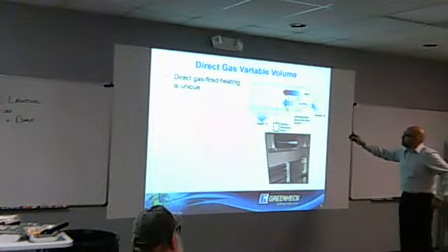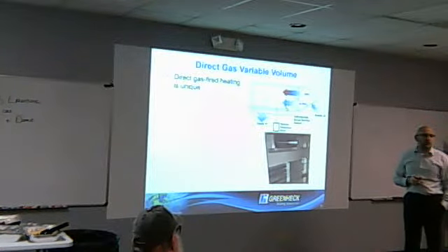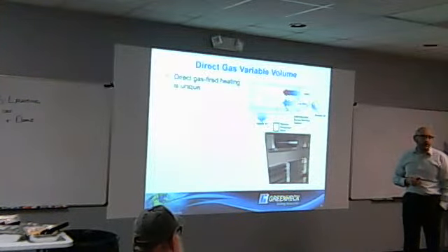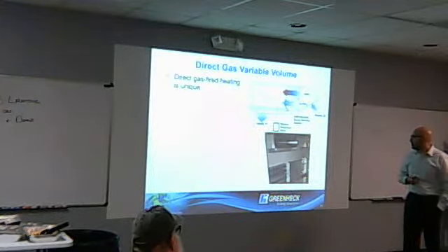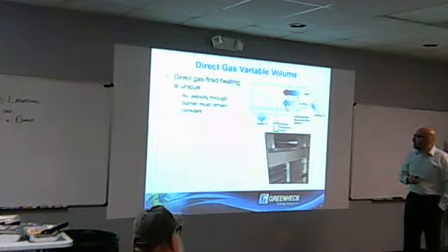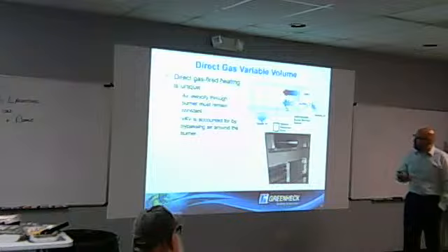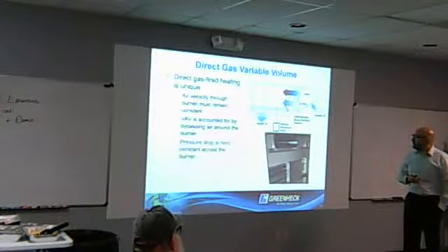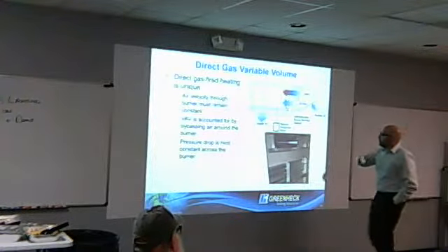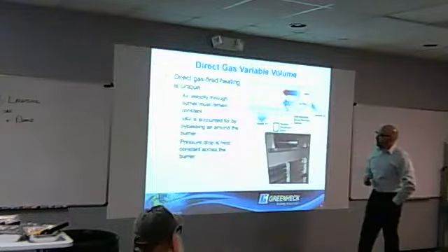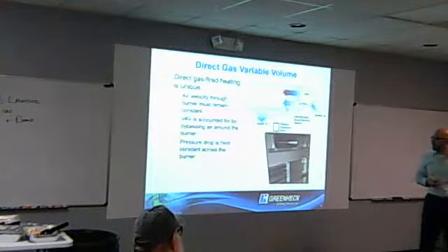So we can't get to a bad condition. It's a combination of the automatically adjusting bypass damper and the fixed profile dampers. Yes, you got it. Dialed in. Air velocity over the burner remains constant. VV is accounted for by the bypass. I mentioned that variable frequency earlier. We have that one, and then the pressure drop is held constant.